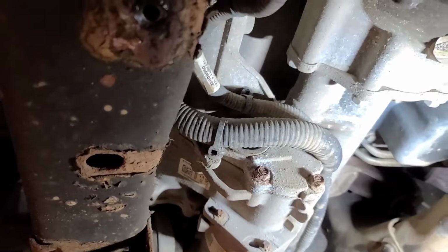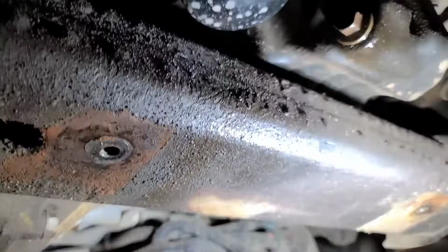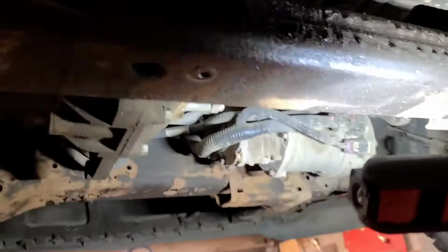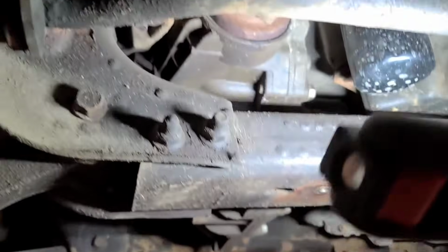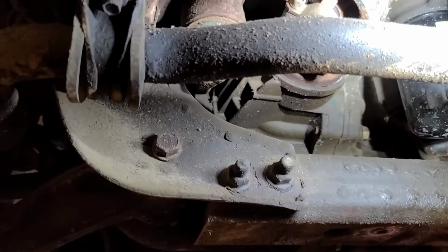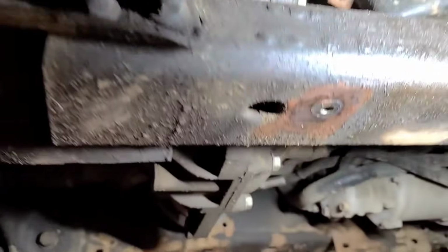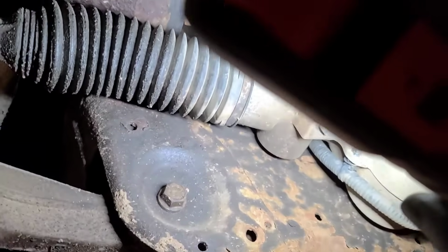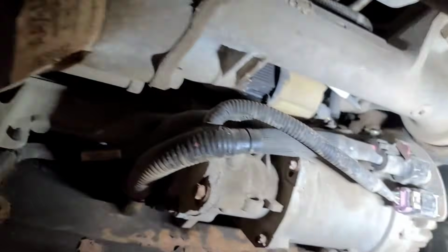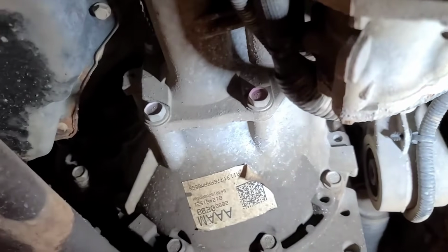There are two braces that go across the bottom here that have to come off. So we have to remove this power steering gear, which is electric. We have to move the front differential, engine oil pan. This cross member here has to come out. Disconnect the front axle shaft or drive shaft at the joint here. Disconnect the CV shafts at the inner tripod joints. Tie rod ends, it's going to have to go for a wheel alignment after. Wow, there's a lot of work here. Way to go, GM.